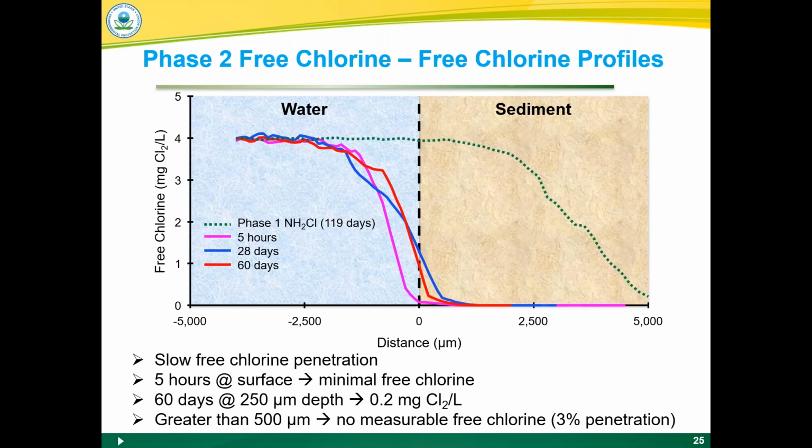So again, free chlorine hardly got into this at all compared to the monochloramine, only about a 3% penetration. So only the first half a centimeter, or first 500 microns. So it barely penetrated at all. Again, much more reactive, not penetrating.